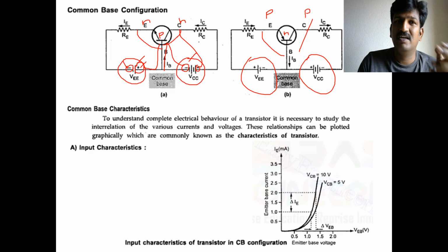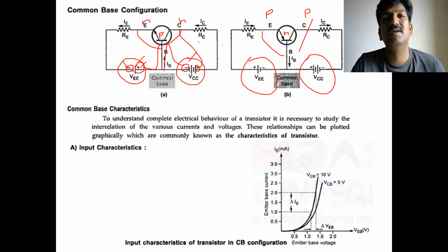If you do not want that particular junction to conduct, you have to make that junction reverse biased, so exchange the polarities. The N-type needs to be connected with the plus terminal and the minus polarity of the battery connected with the P terminal. Then the particular junction is going to become reverse biased.